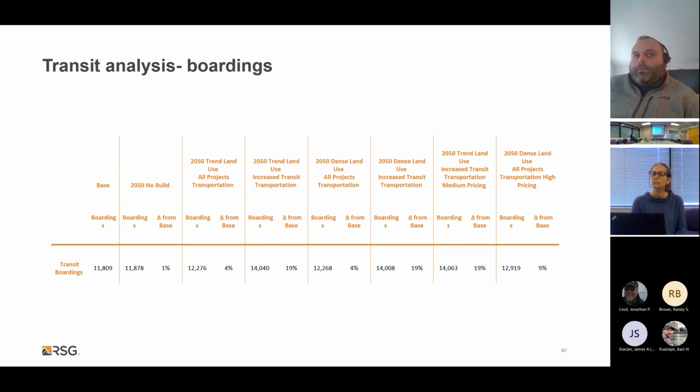It depends on where the target is at the calibration. If you're wanting to have a model that is calibrated at route level, then you have to have an OD survey that matches with the routes that were estimated at the time. Otherwise, if you change the routes, say you had 5 routes and you expanded that to 25 routes, the survey would only be sensitive to 5 of those routes, and those routes might not be valid anymore.